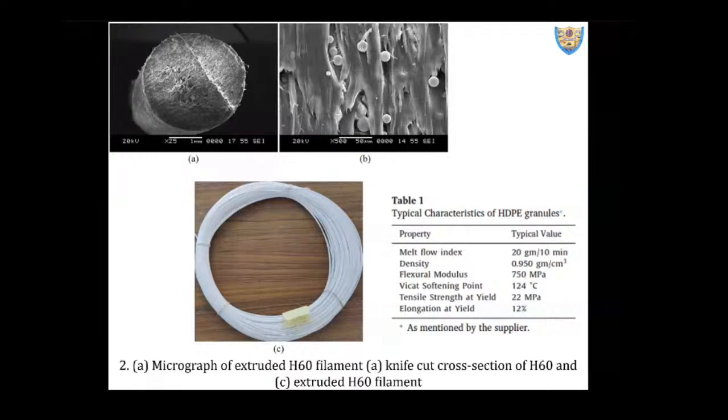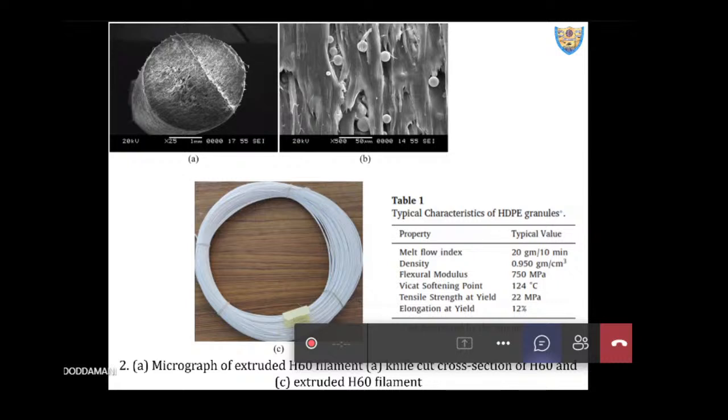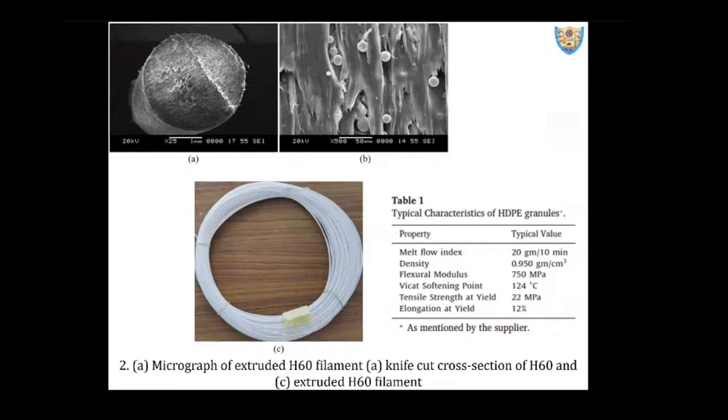So blending is carried out at an optimized speed. Again, when I say optimized, a lot of trial and error has gone into it. So we carried it out at around 160 degrees C and at a polymer blender speed of 10 RPM. And we infused 20, 40 and 60 percent by volume of GMB in HDP. Now these three different volume fractions, we denote henceforth. If you see some numbers as H20, H40, H60, H is for HDP and 20 is the volume fraction of the filler which we have used. So these blends of H20, H40, H60,